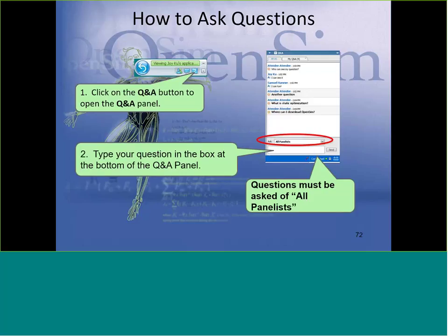And I would just add to that, just question. If something doesn't look right, just because OpenSim predicted it, don't assume that it's right, question it. So for us, when we started seeing passive force, I mean, you don't even have to do a simulation. If you just take the model and flex the knee and look at what the passive forces are, when the knee is really flexed, the forces can get really large and they're just not plausible over those ranges of motion. And there's experimental data you can go and check and see how it compares to what you find in the literature. But you just have to really question every step.